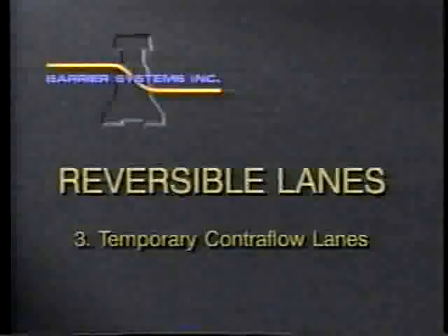Movable barriers can be used to temporarily separate traffic on one side of the highway while the other side is closed for work. For example, the Van Wyck Expressway is a major 6-lane arterial in New York City, carrying 180,000 cars per day. To repair and repave it in an expeditious manner, the New York DOT designed the project so that the Quickchange movable barrier was placed next to the existing median, and every night it was moved out a lane to form a divided highway on one side of the roadway.